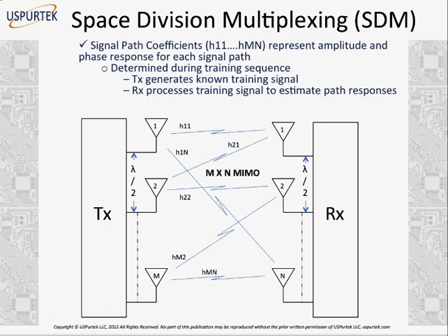Now, how do we determine this? This is a physical channel. So there is a training sequence which is initiated before a transmitter and receiver can even exchange any data or information. Like you switch on your MIMO phone and try to connect to your MIMO transmitter, the first thing that will happen is a training sequence. That means both transmitter and receiver will try to find what all beams are available between them. That is called a training sequence, and all wireless standards have a specification for training sequences.